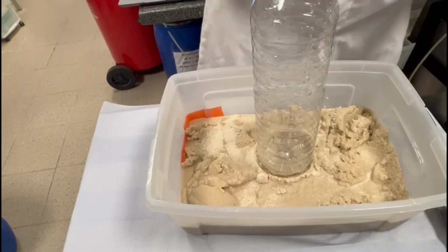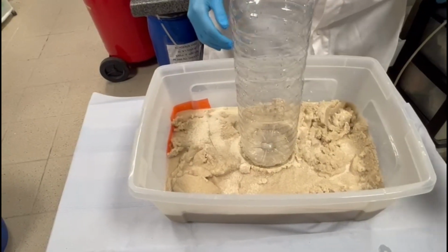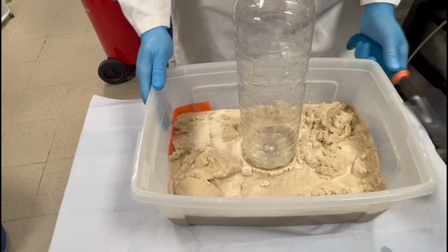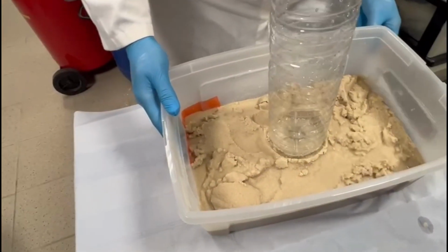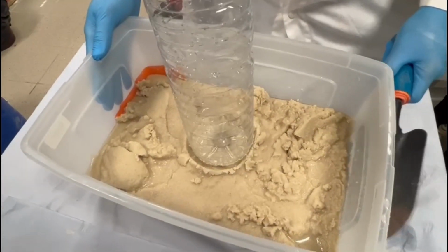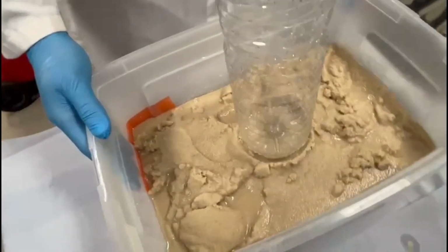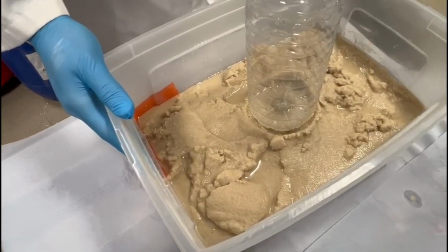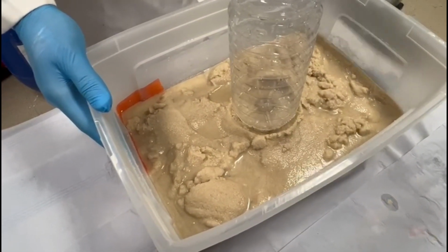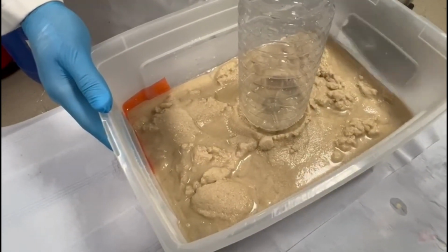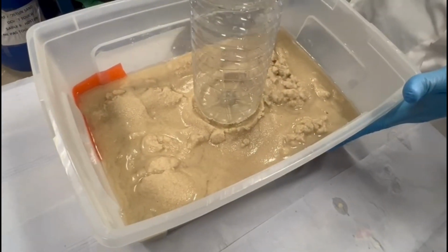As liquefaction occurs during an earthquake, we will tap on the container to simulate the vibrations of an earthquake. As you can see, the soil around the building starts to saturate directly. That will eventually lead to liquefaction, meaning that the sand will start to act as a liquid. The building itself will resist the vibrations, whereas the soil particles will lose their connections and the sand will lose its strength, which will cause the building to sink inside the soil.